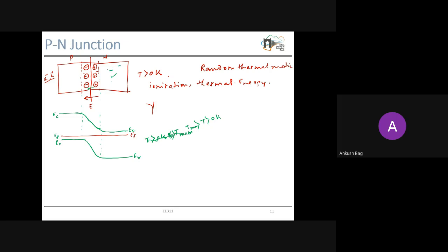Will this electron be able to cross this interface and meet another hole here, or will this hole jump over this built depletion region and meet another electron here, so that there is more uncovering of ions, and then the depletion width WD will keep on increasing? Will this keep on happening, or when will it stop?